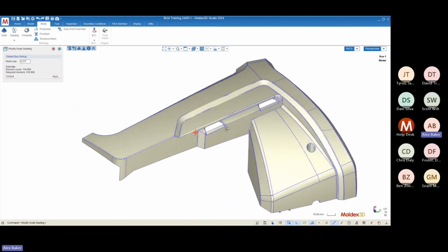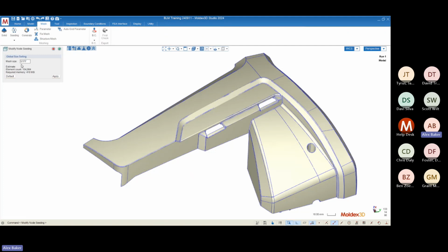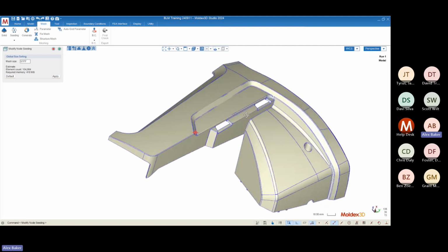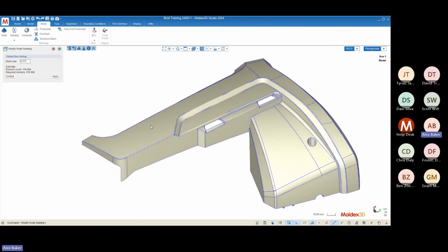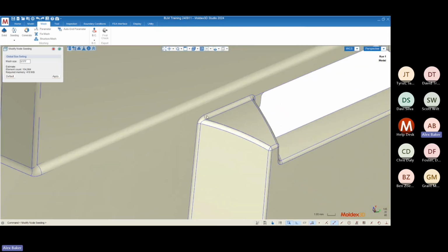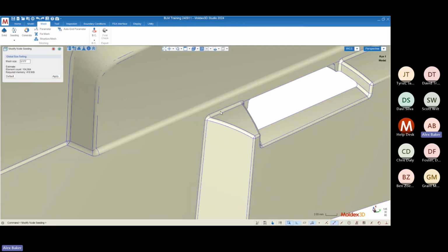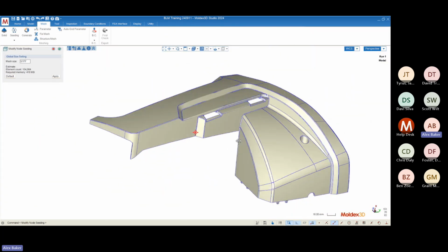For any sort of complex geometry like this, or even a little bit more complicated than this, default node seeding is very, very good. But just know that if you have a simple geometry, it's kind of counterintuitive actually. If you have a more simple geometry, the default is a little bit less accurate. And the reason for that is just because there's less of a diverse array of feature line lengths. And if that's the case, then it can't really determine a good node seeding.